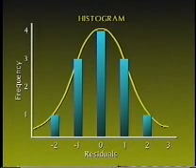This graphical representation will highlight any values that might contain a systematic error or a blunder that were not removed prior to determining the mean. These will appear as spikes or valleys in the histogram. If these are present, they should be removed and the mean and residuals recalculated. Steep-sided curves indicate high precision. The residuals are grouped closely together. Shallow-sided curves indicate low precision. The residuals are more spread out.